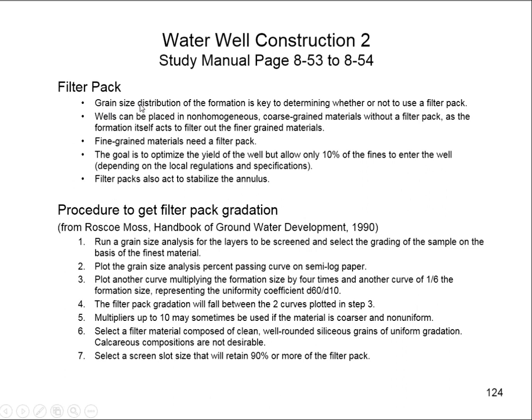Filter packs. This would go into the annular space around the well, and whether or not you need a filter pack depends on what the formation is. If you have homogeneous, fine grain materials, you need a filter pack. And anything like a coarse grain material, non-homogeneous, you can get away without using a filter pack.